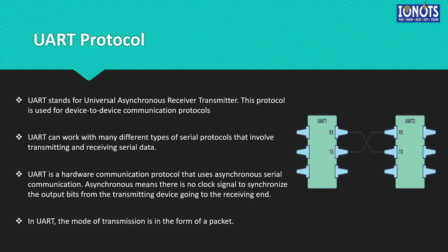The main purpose of a transmitter and the receiver line for each device is to transmit and receive serial data, intended for serial communication. This is also a serial communication protocol. The transmitting UART is connected to a controlling data bus that sends data in a parallel form. From this, the data will be transmitted on the transmission line serially, bit by bit, to the receiving UART. This, in turn, will convert the serial data into parallel for the receiving device.